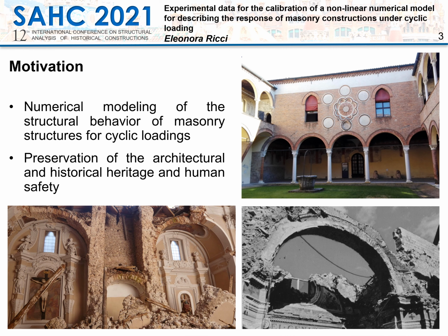In fact, while the static analysis of arches is widely investigated, a better understanding of the response of masonry vaults and arches under dynamic loading conditions is necessary for the evaluation of the behavior of the structural elements, especially when located in seismically active areas. A first step in this direction is the study of the structural response under cyclic loads.